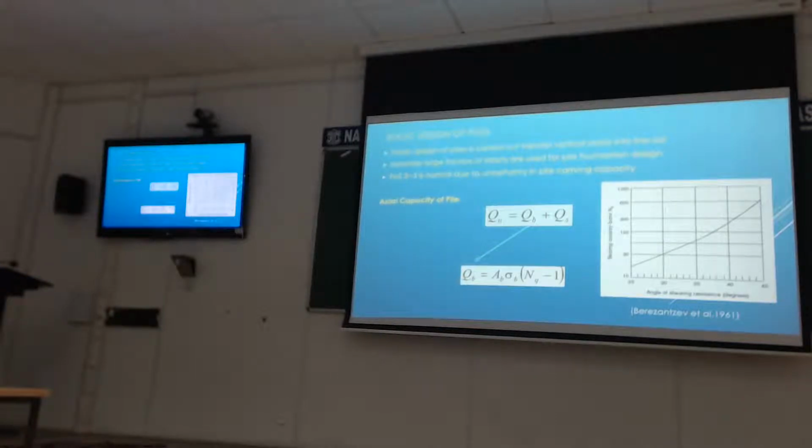Static design is normally where you're designing the piles to carry the vertical load into the soil. The horizontal loading part we will do separately later on. As I said earlier, we tend to use quite a large factor of safety for pile design, between 2 and 3 is quite common. So all of us, we've done this already.